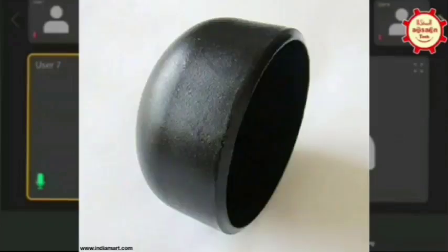No, what is your issue? You have a seamless pipe with both sides end caps. It's closed, yes, both sides end cap. Also, we have a circumferential seam in the shell pipe. No, wait, you mean you have a circumferential seam in the pipe also? Yeah, correct. Oh, you have both cases. Yes. Then you need to consider 0.85.